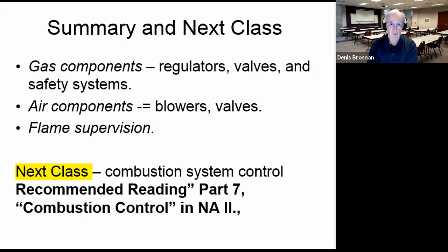We've talked about air components. We've talked about using our senses to know if the gas is on or off by looking at the position of valves. So these are very easy things for you to think about. You can always hear the centrifugal blower for combustion air, so you know it's on. That's another way of using your senses. And you have flame supervision in order to make sure that combustion takes place.